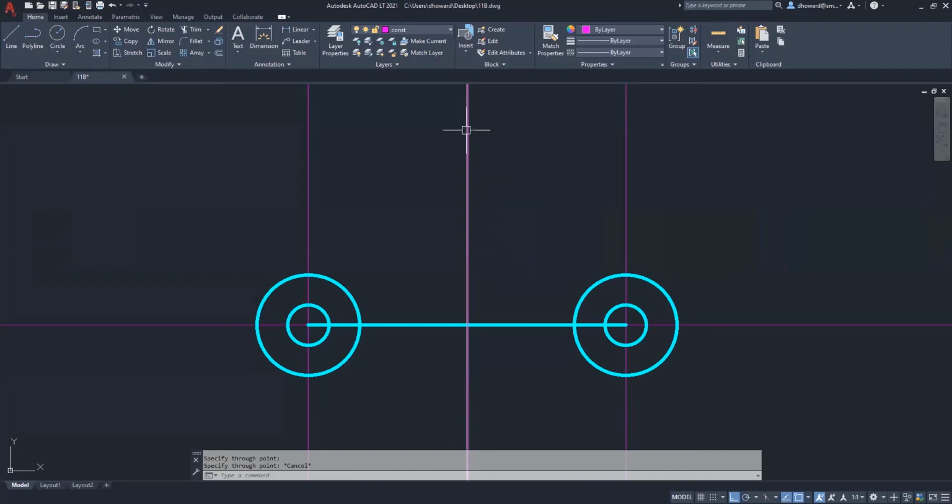I also could have offset half that distance, but rather than do the math, which would have been dividing 3 7/8 by 2, which is a little tricky, I just did this other trick, which is just clicking on the midpoint of a line that connects them. So that works out pretty well. And now I can just delete that. So I've got my object's center line here, and I am ready to offset it on both sides, and this one on both sides to find that rectangle.